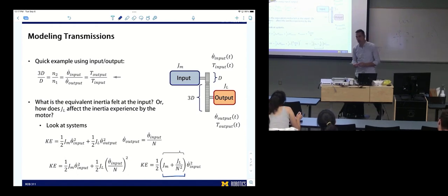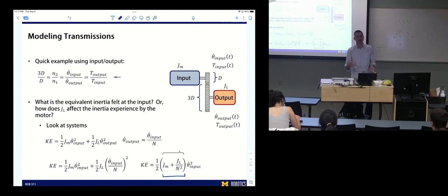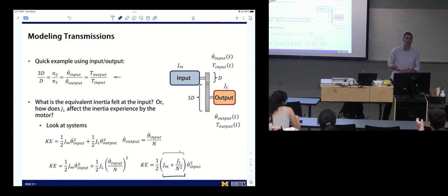Yeah, good question. So what happens when you run a motor in negative power? It would generate the power. It generates energy. So if we're talking about robots, maybe we have to carry our power sources, we often want to use that energy. We want to regen to save this energy. If you use a non-backdrivable transmission, you cannot regenerate any energy. Okay, so it's kind of like how Tesla does backdriving with their brakes, right? Definitely. So yep, that would be a case for it.